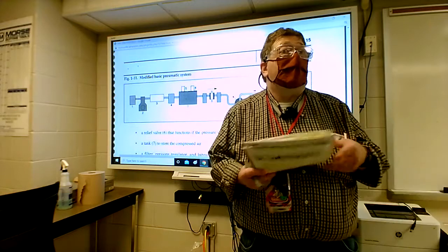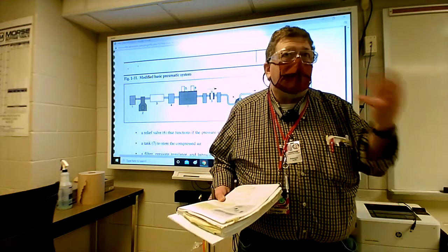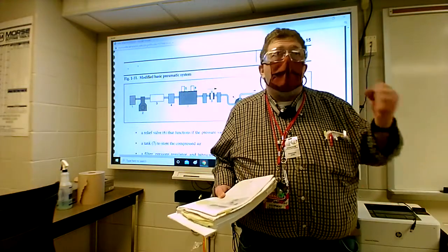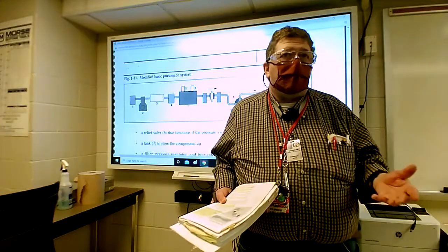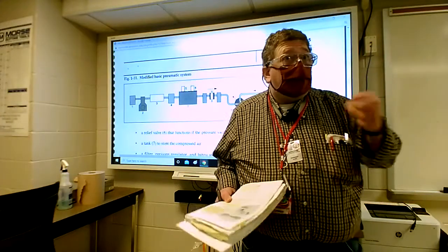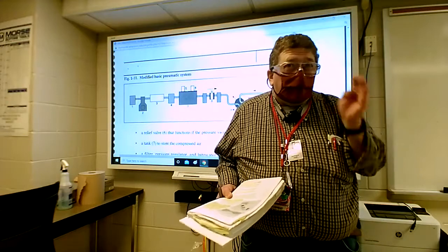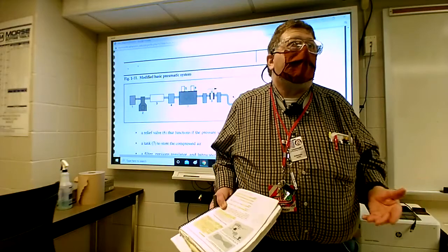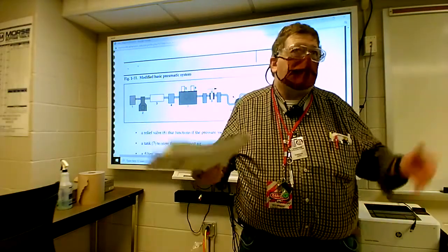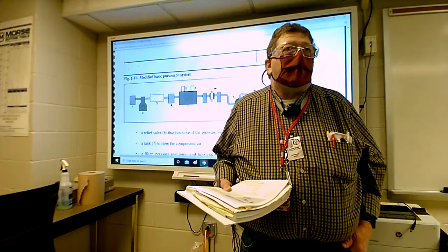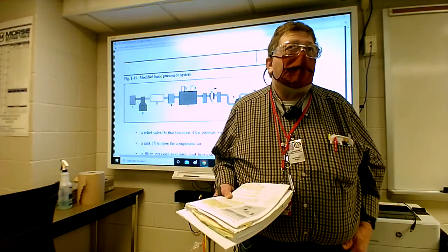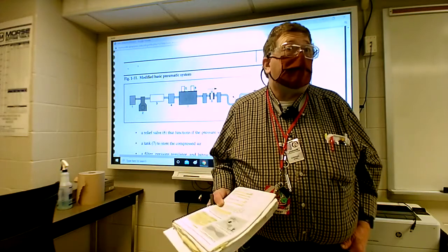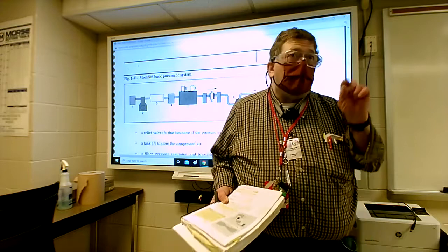You get oil in it because there's leakage within the compressor itself, within the mechanical parts of the compressor. You get oil naturally because of the oil in the compressor. Some of that seeps through and it gets into the output, and it ends up in the airline just through natural leaks. The compressor leaks a little bit. It's coming from the internal part of the compressor. The oil that lubricates the compressor itself actually ends up in the airline. A little bit of it does disperse.